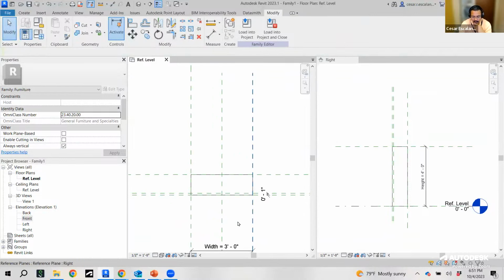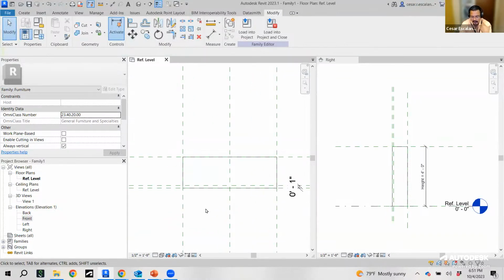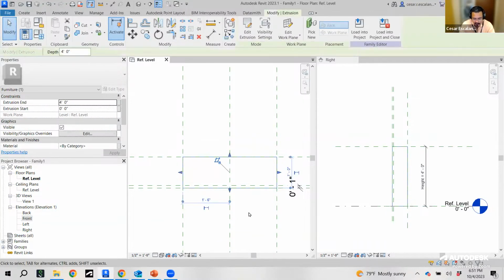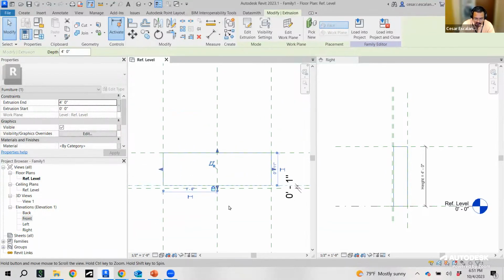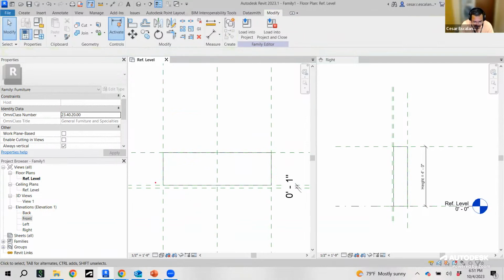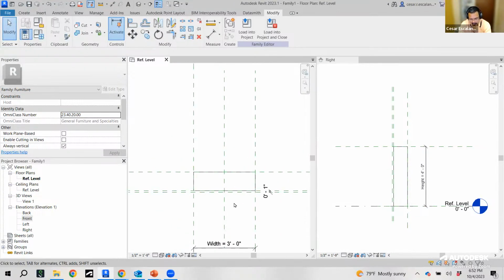Okay. And now what I'm going to do next is to open the space for the door families. So select the cabinet in the floor plan, grab the handle associated with the front. I'm going to snap it to the new reference plane I just created and lock it. The reason I'm doing that is that I'm going to bring a family of doors, and I'm opening space for the doors. Any question here? You want me to repeat anything?